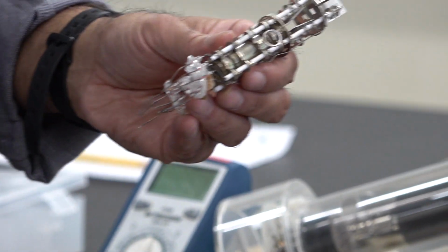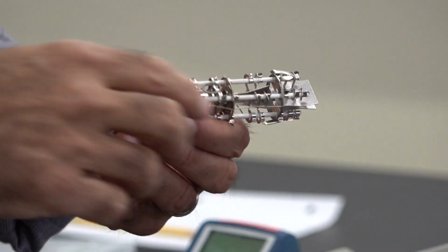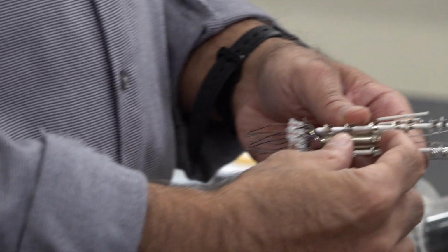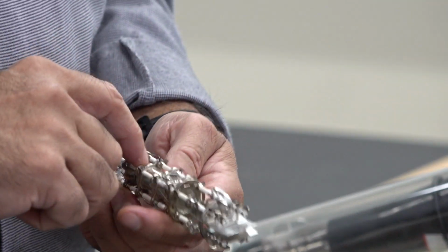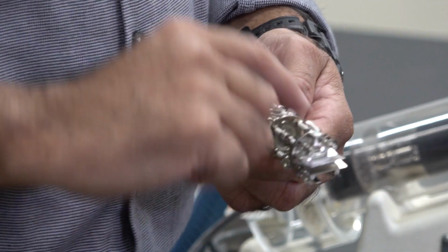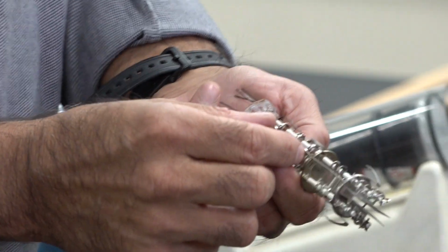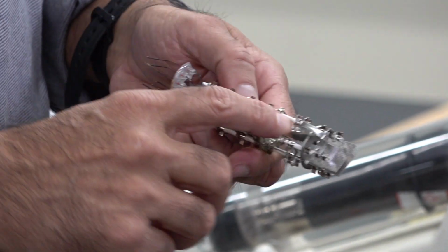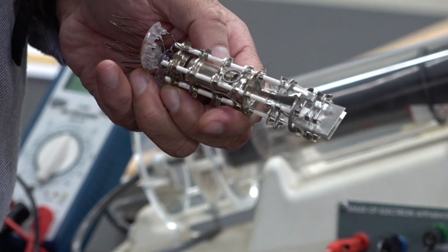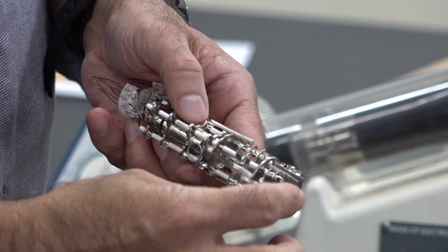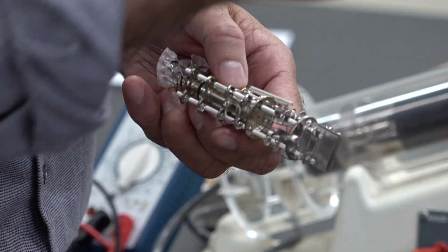So all the bias voltages are applied here, and the current goes into this over here. There's a metallic part where, when you put current into the metal, it emits electrons. And then you have a very high voltage, 500, 600 volts, which will attract the electrons through that length. And when it comes out here, you put a bias voltage here, and the electrons can either go up or go down, and you can put another bias voltage here in the X, and then it goes to the side.